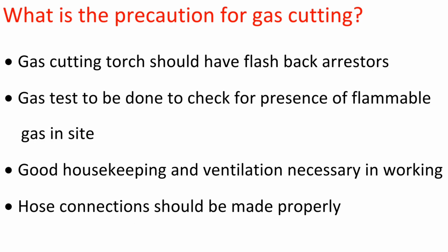Gas cutting torch should have flashback arrestors. Gas test to be done to check for presence of flammable gas in site. Good housekeeping and ventilation necessary in working. Hose connections should be made properly.